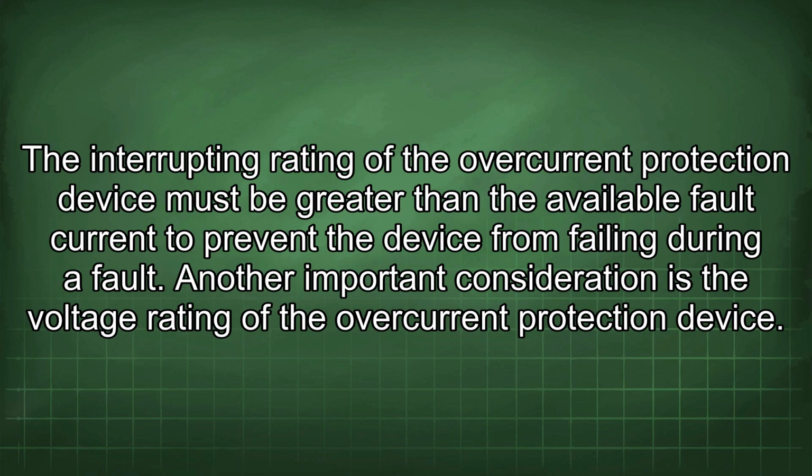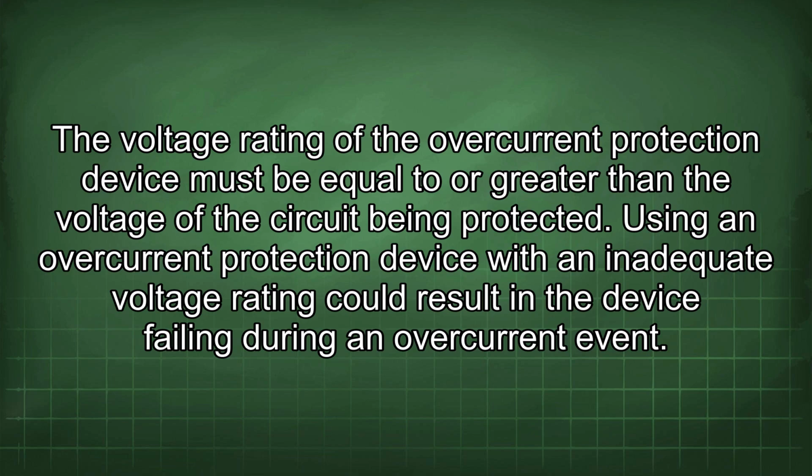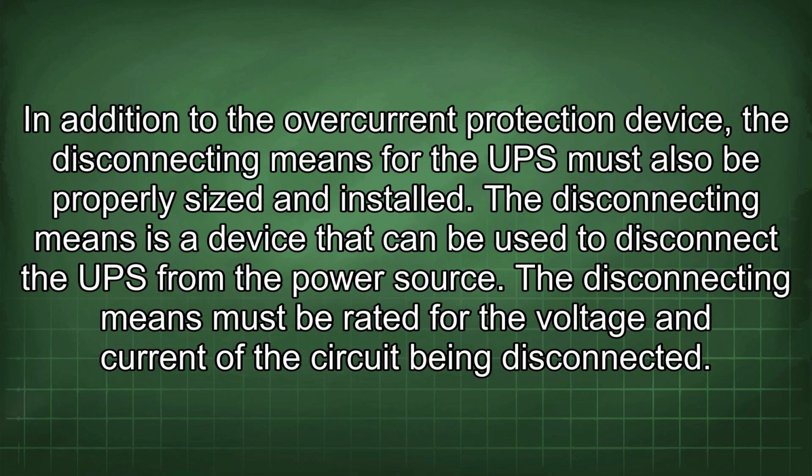Another important consideration is the voltage rating of the overcurrent protection device. The voltage rating of the overcurrent protection device must be equal to or greater than the voltage of the circuit being protected. Using an overcurrent protection device with an inadequate voltage rating could result in the device failing during an overcurrent event. In addition to the overcurrent protection device, the disconnecting means for the UPS must also be properly sized